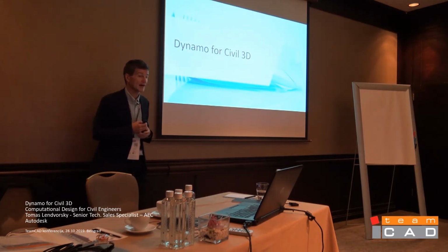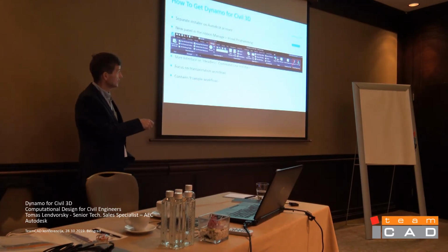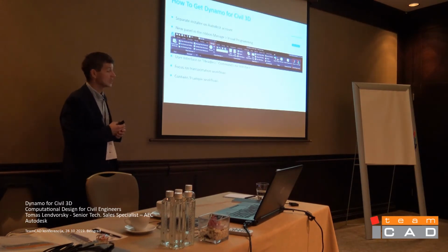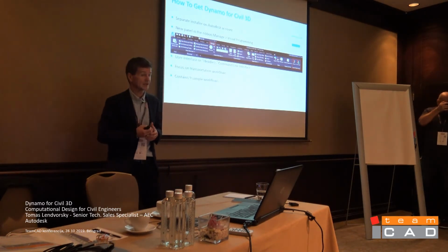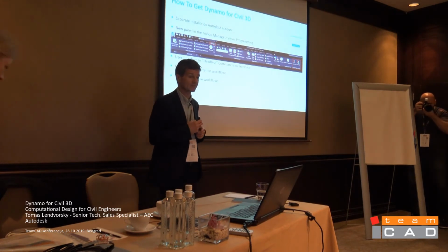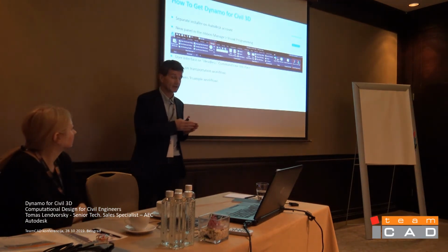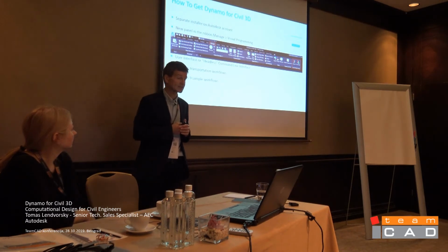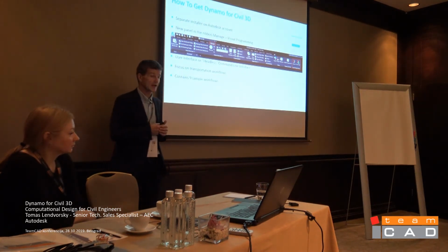So let's have a look at how Dynamo for Civil 3D looks. Within the ribbons, we have one new tab, which is Dynamo, and you can run Dynamo scripts. It appears in Civil 3D 20.1, which, as I told you, we released recently, in spring of this year. Another important thing: you are not able to use Dynamo in previous versions of Civil 3D. It must be only the new one, and honestly, we are not going to change it. If you want to use Dynamo, you have to go to the new release of Civil 3D, and of course you can update from your account manager and download it.